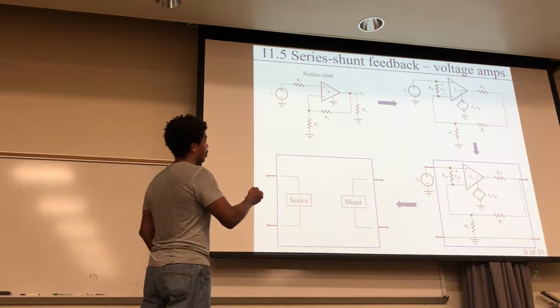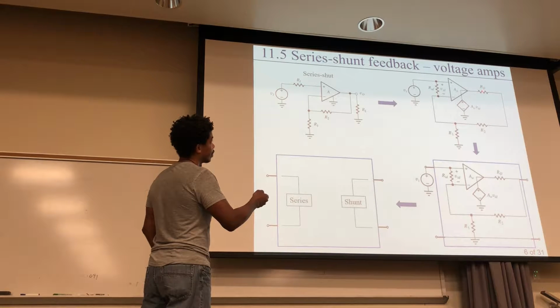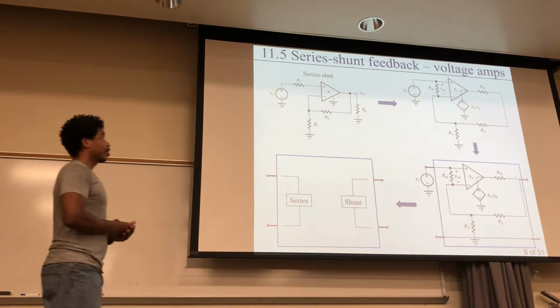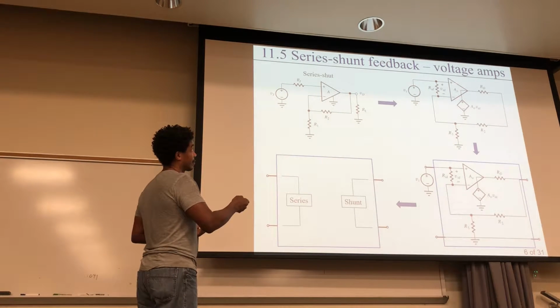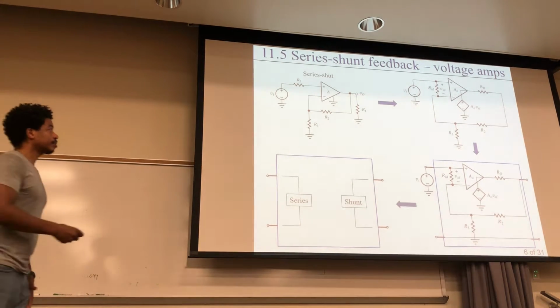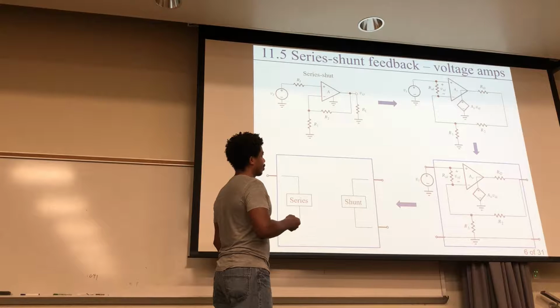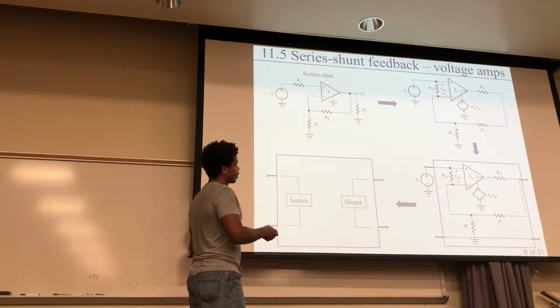And so you can model that by this resistor. It's basically popping it out right here. Okay? And also, inside of there, you have some output resistance right here, and also a voltage-controlled voltage source right here. Okay? So if you want to, you can actually take this, you can remove this triangle right here, and just have all this other stuff without the triangle. Okay, because you basically pulled everything out to really focus on those things. Also, you should note that this is just like the 2-port, right? Putting a box around here. These are the output ports. These right here are the input ports. Okay?